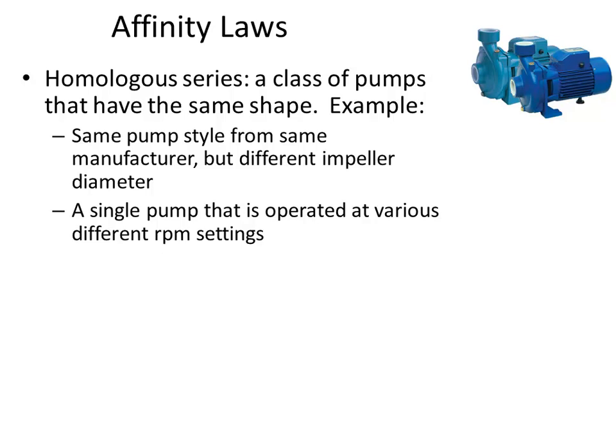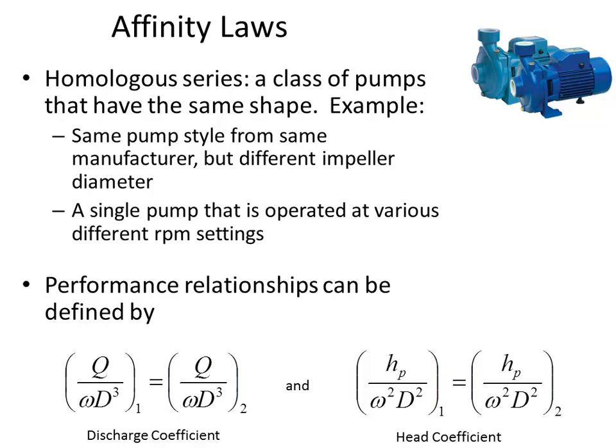And these affinity laws are a little bit like the dimensional analysis things that we did in fluid mechanics, where you're trying to equate the performance of two related things. It's very similar to maintaining similitude and having a prototype and a model. And so there's a discharge coefficient and a head coefficient.